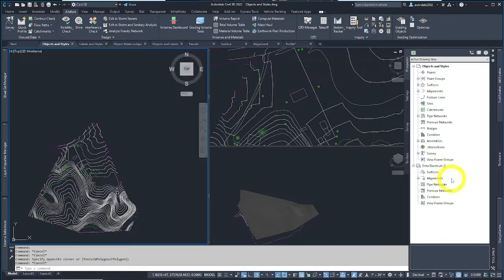And really it's just sharing the data in a dynamic Civil 3D environment as we learn through data shortcuts at the end of Chapter 2, a way to link objects and styles and labels and label styles between drawings. So multiple users can edit between drawings in different phases of a project depending on how the drawing is set up. Drawing setup is not an easy thing for a beginner CAD user of Civil 3D. It takes a lot of practice in what works and what doesn't.